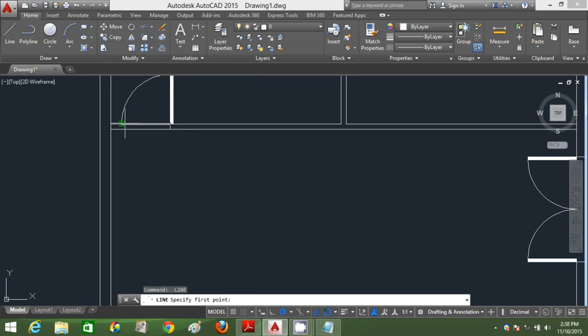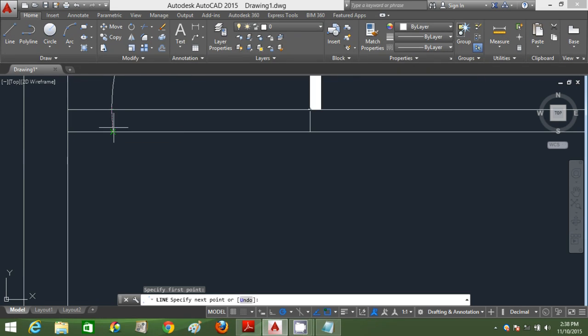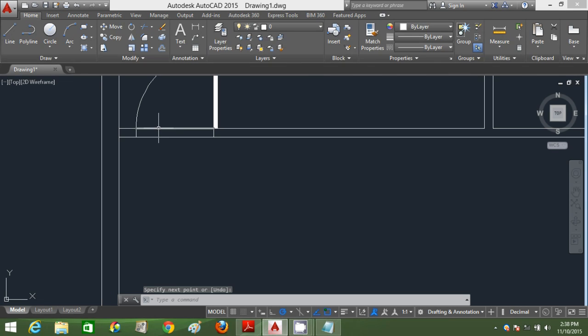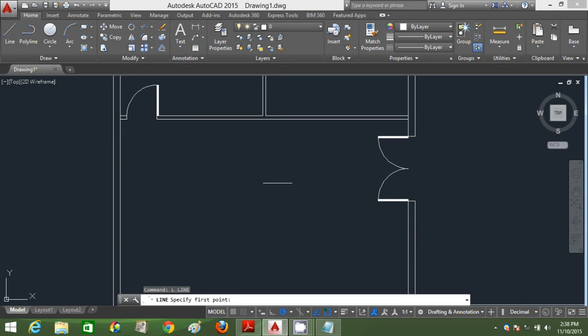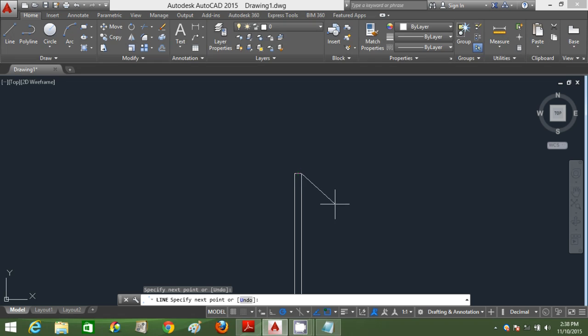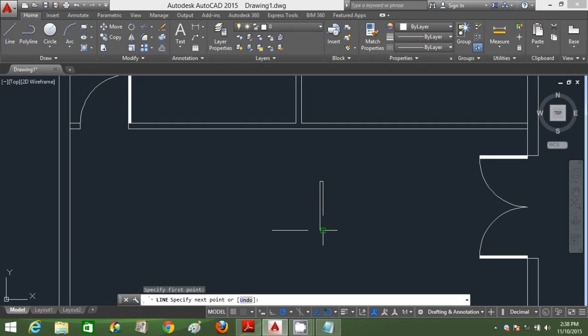I'm creating the boundary for the door. Click line, draw that line properly straight. Select the overlap line, delete it, and trim out these portions. I have to delete the overlap line first before trimming. Okay, now I'm drawing another door. Type 900 mm as its length, offset it by 50 mm. Close the particular portion, close that particular portion.